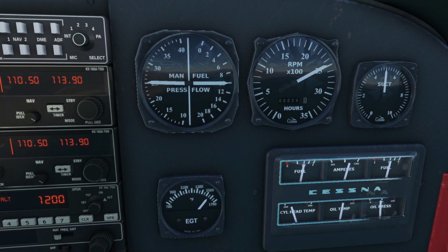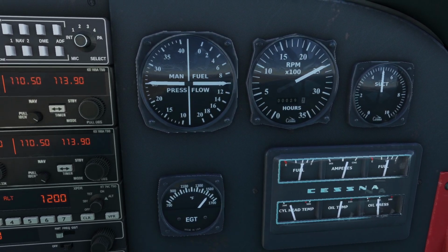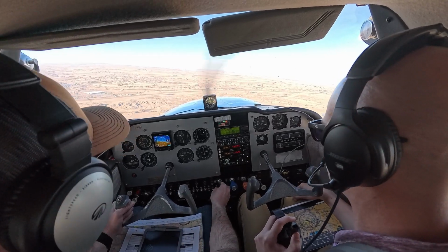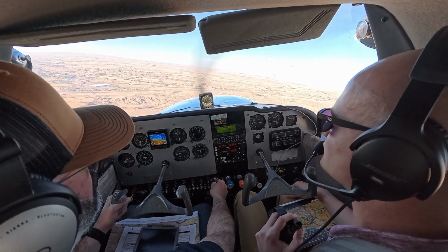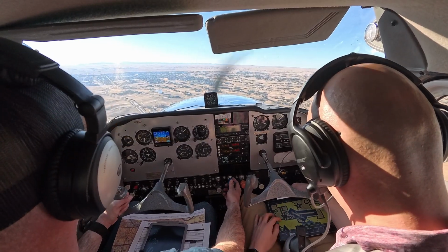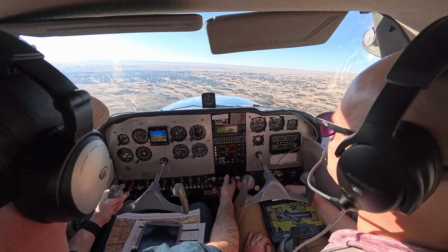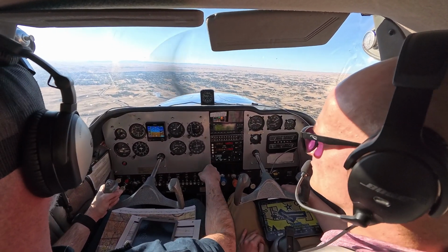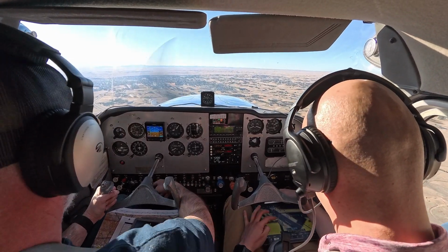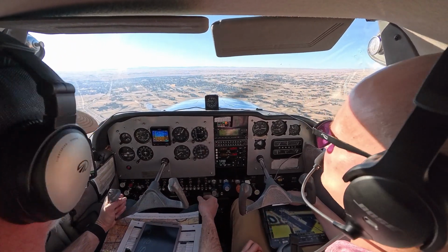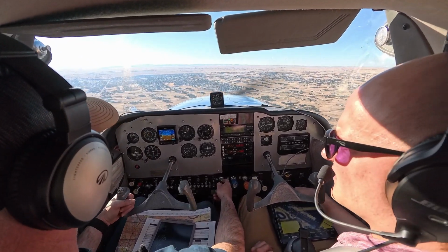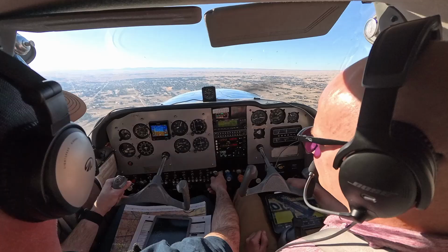Generally, as you start your descent, you can leave your propeller lever where it's at and just reduce throttle like you normally would in a fixed-pitch propellered airplane. As you enter the traffic pattern and prepare for landing, you will adjust your propeller knob all the way forward to a high RPM setting. It's important that we do this as a before landing check and not as an approach check. We don't want to operate the engine at redline for long periods of time. So do this as you are nearing the final approach.